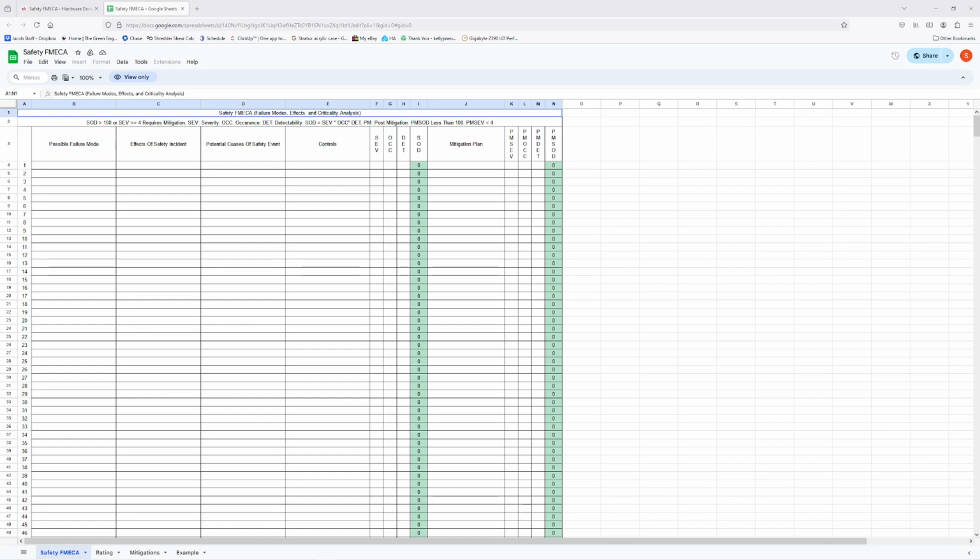One of the ways that you can easily do it is assume that your product is not safe, assume that everything can happen, and prove that it won't happen. Give yourself a very high reasonable doubt that it will not happen. So let's say that you have a car and you're worried about your upper or lower control arm coming off. And you say, okay, what are all the different ways that the upper and lower control arms can come off? Oh, they can come unbolted. Okay, well, how do I make sure they don't come unbolted?